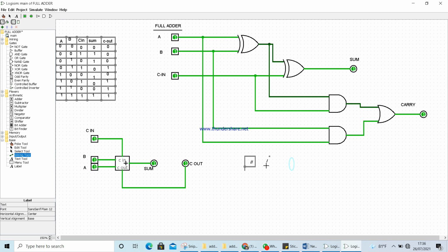There is no other pair, there is remaining only one. So what will happen is this 2 group is another 1 group, and you will be remaining 1. If you add this, this 1 is this grouped 1, it is the carry, and this is the summation 1. So this is the simulation of full adder using the logic gates and also from the circuit.